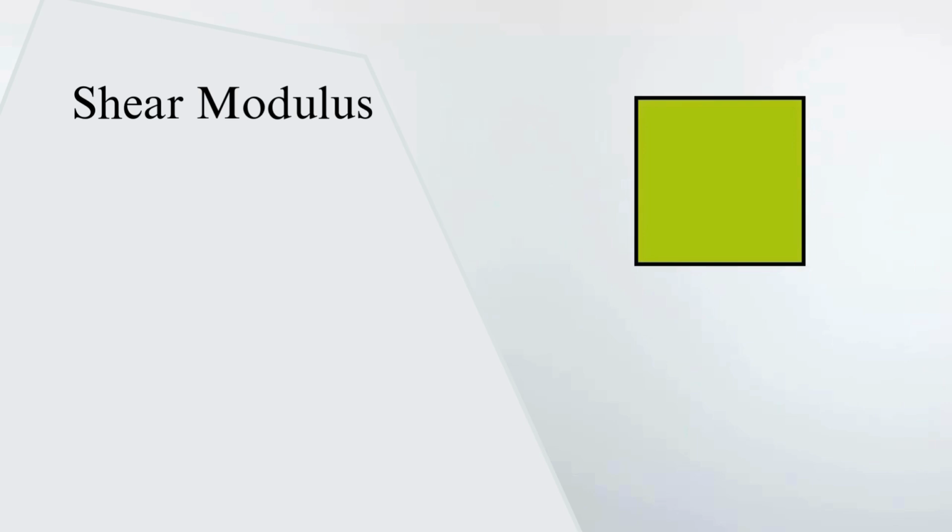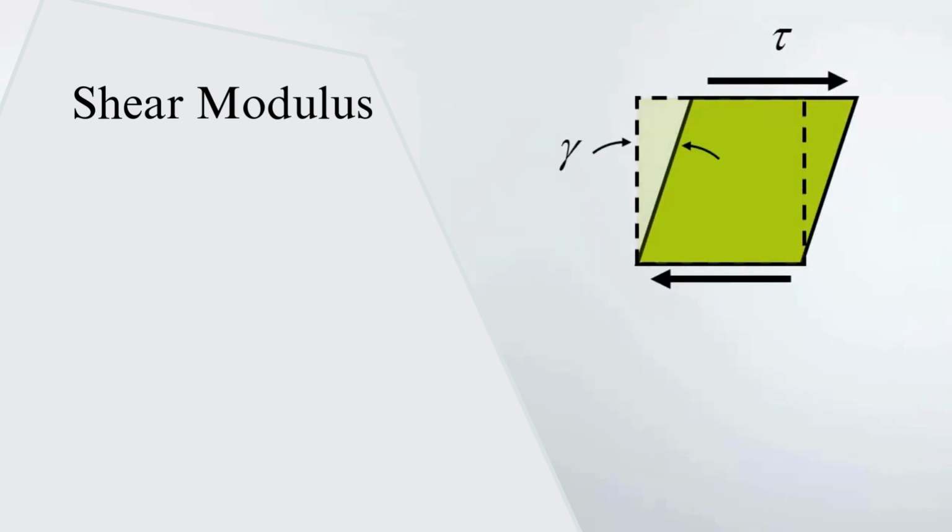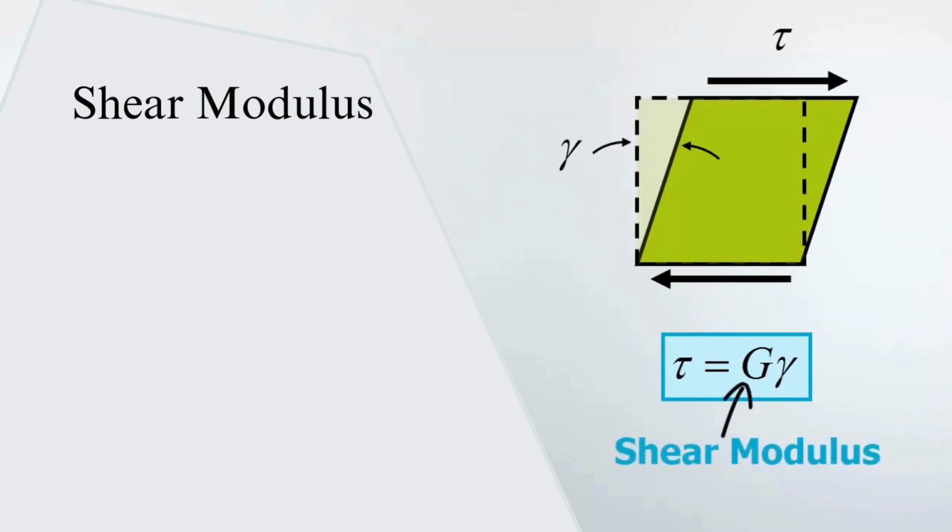So far, we've looked at the relationship between normal stresses and normal strains in a material, but not shear. If we conduct similar experiments where we apply pure shear loading to a material and measure the shear strain and plot the behavior, we also observe that the shear strain is linearly proportional to the shear stress. There is an analogy to the Young's modulus for shear. We call this the shear modulus and denote it by the letter G.